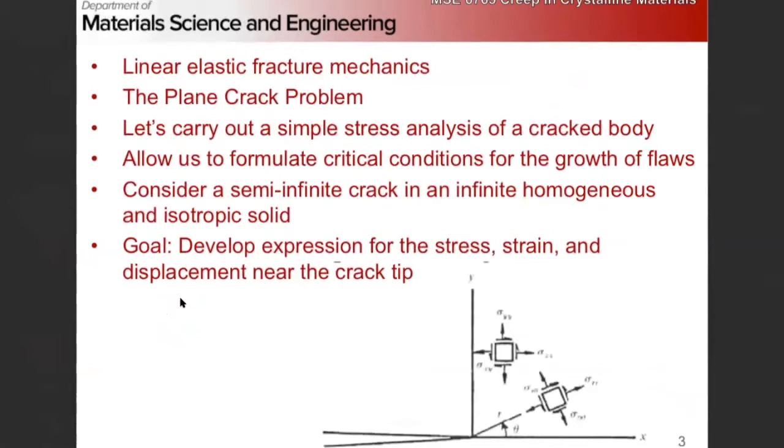Okay, so what do we mean by semi-infinite crack? Right, so this is our plane. This plane is infinitely large, and this crack goes from 0 to negative infinity. Right? It's exactly halfway through our infinite crack. All right, and the rest of our uncracked region goes from 0 to positive infinity. Right? And what we want to do is develop an expression for stresses and strains and displacements near this crack tip.